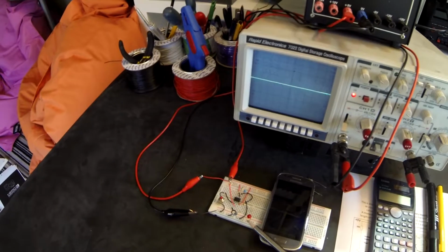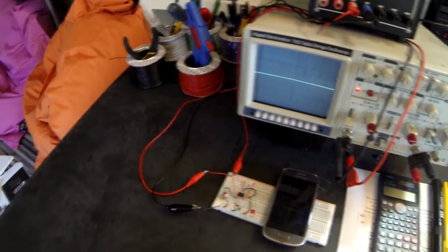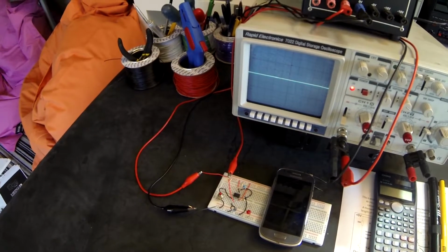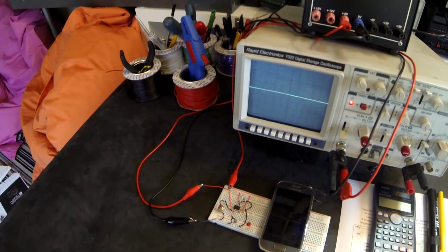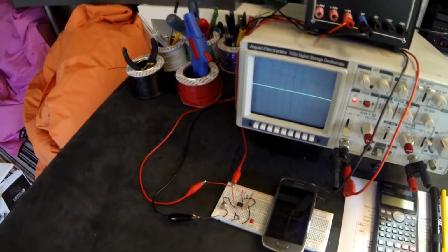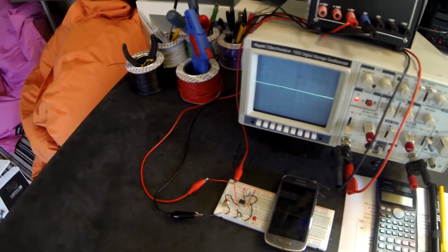Now our stable state is actually when the LED is currently off, because that state is stable because it will not change unless we do something to change it. When the LED comes on, however, it is considered the unstable state because it will not stay on forever. It will automatically go off dependent upon the values of R and C.